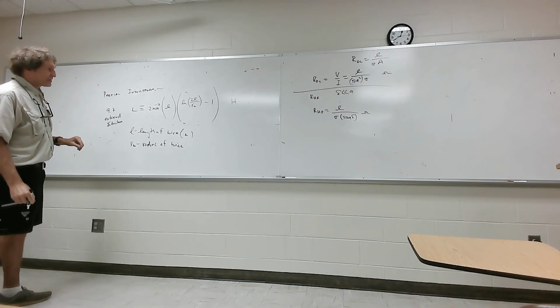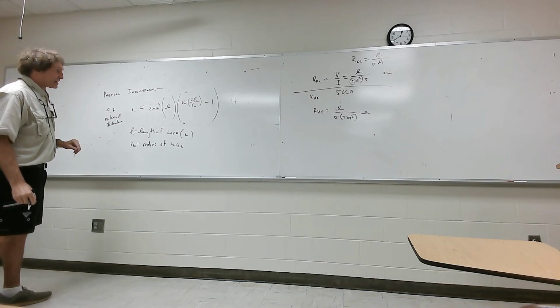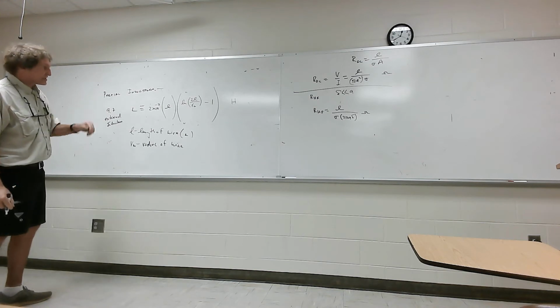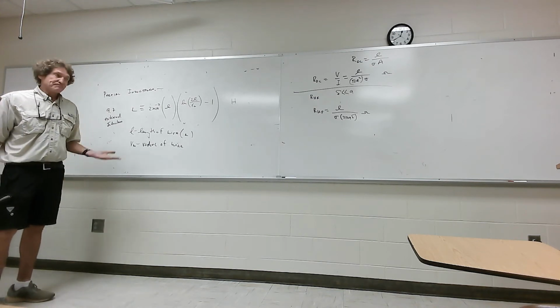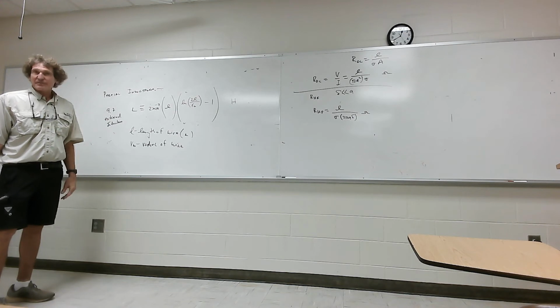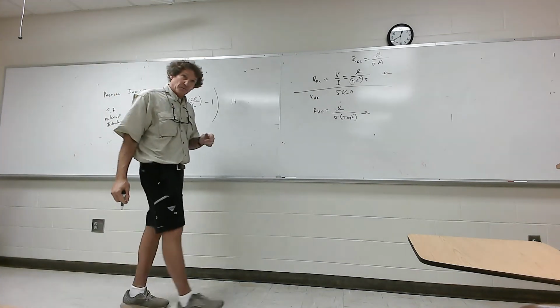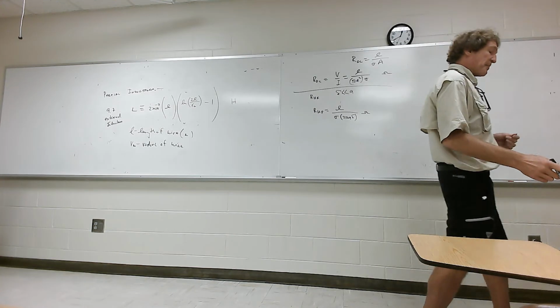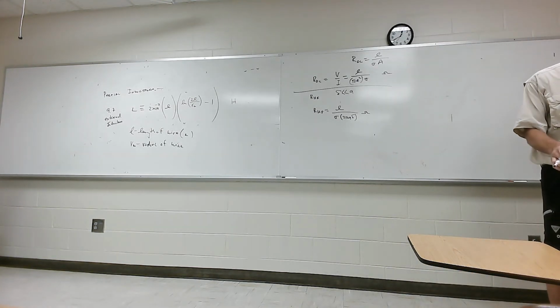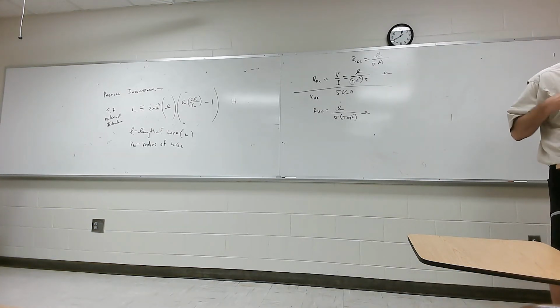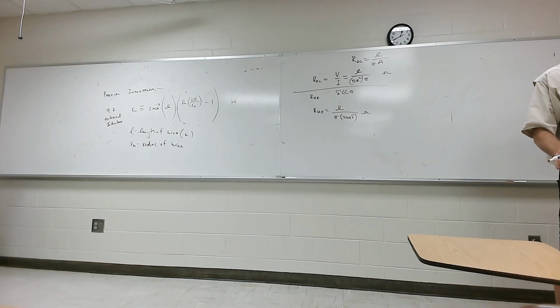Now, I want to tell you one thing. How accurate this thing is, I'm not absolutely certain. I know it's been developed and used by a lot of people in the real world when they're trying to estimate the external inductance of wires where they don't know the entire return path. But it is used, so I'll just leave it there. He says that in his book, the formula is based on partial inductance, a subject which is beyond the scope of this text. Basically, he doesn't want to mess with it.